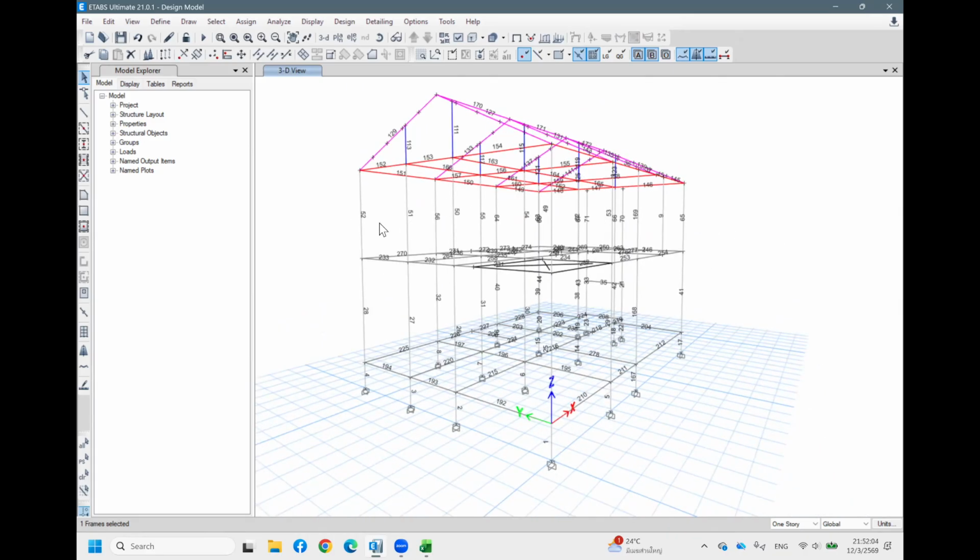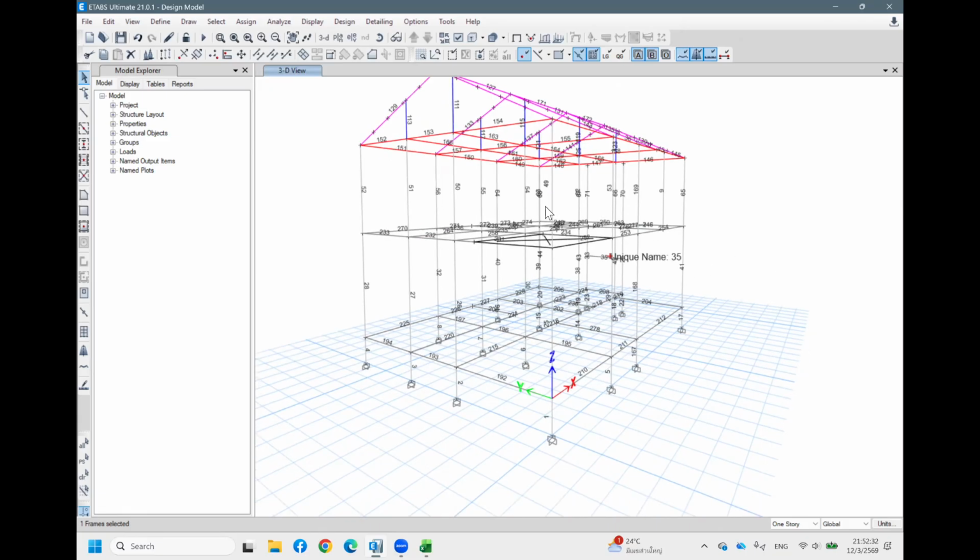So we need to use these as assumed sections only. So if we want to check whether our design passes or not, we need to create a design section. For example, my beam, I use 2 DB in the top and 2 DB in the bottom, and I want to check whether it passes or not due to the moment, due to the load that we apply. And the same for column. If I just use 4 DB in 4 corners, can it resist the load or not?